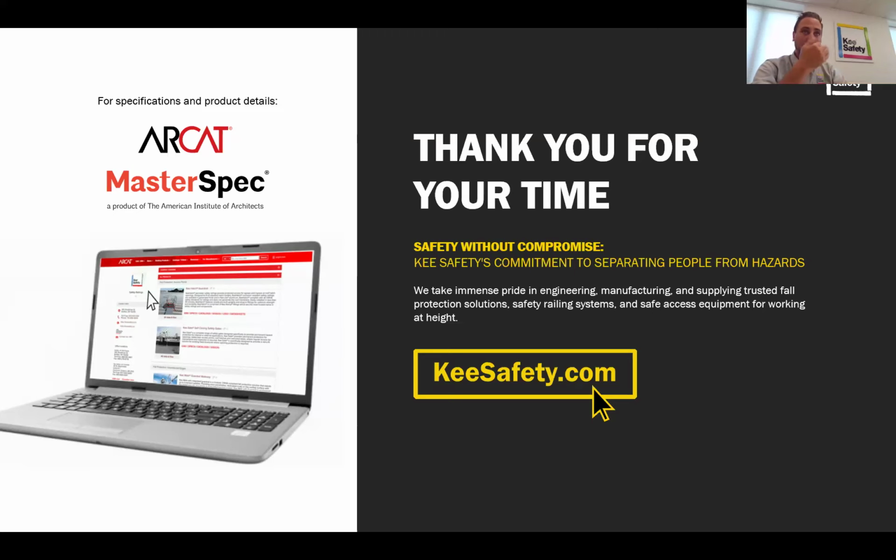I'll give you an example, because we have partners that we work with every day that go out and inspect these and you have to pull test them. Looked at the anchor, it's flashed into the roofing, right? You have a flat roof, it's flashed. Everything looks good. You do it one of these, it feels pretty sturdy. Okay, cool. They test it anchor to anchor. They put the chain on it. They start to pull in. It folds right over. And they're like, what's going on?